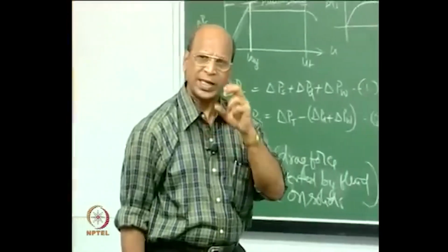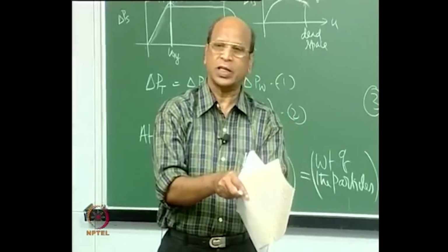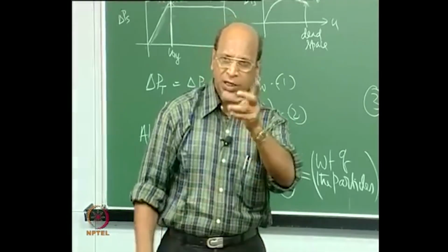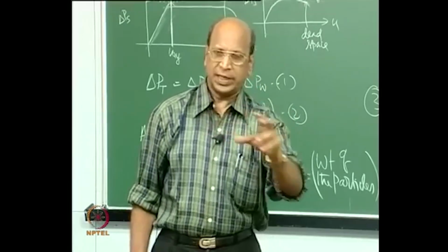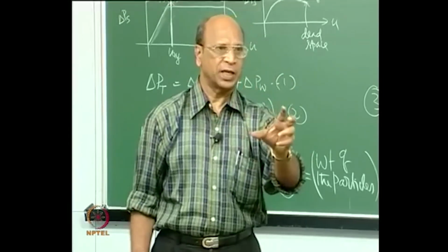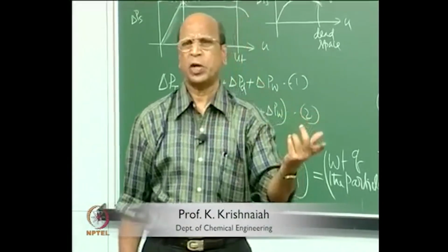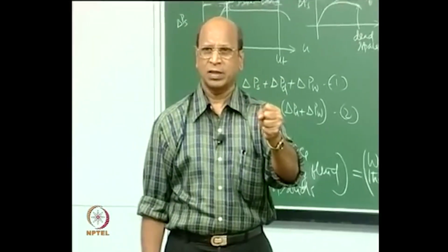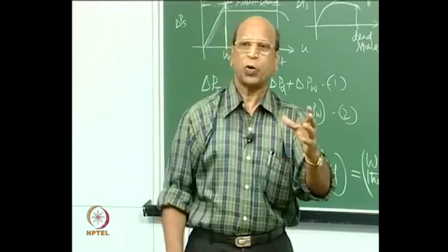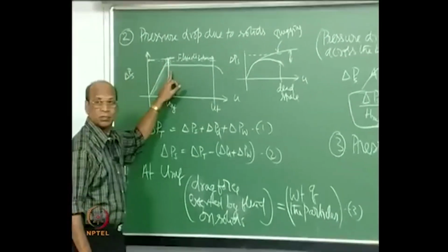Why does it have to lift the bed? Because all the particles are coming together. If each particle is individually present, then the gas will exert the drag force on each and every particle, so uniformly it will fluidize. But normally we use fine powders, so it has that surface energy where it will come together and cling together. That you have to break before fluidization. So, that is the reason why it goes slightly above.